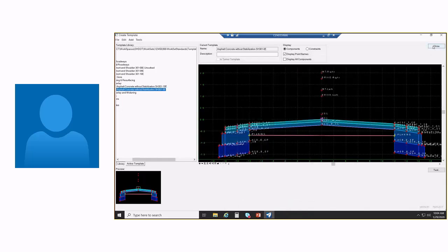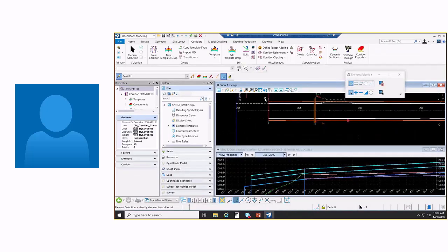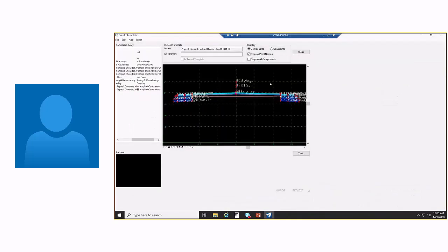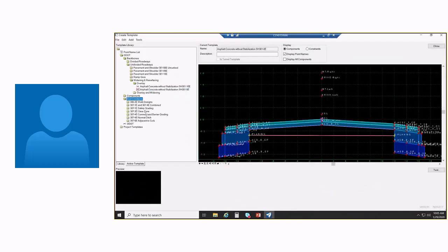So to some of you that have been using this, that probably makes sense. But you'll know it's a problem if you assign a point control and it doesn't apply. If there's a feature name override assigned, then that's a bug currently. Anything else I need to mention? You typically see it when you're doing your ditch profiles, because the ditch point, that's where the majority of people see it. Yeah. And they go, why isn't that ditch point showing up? That's why. Just go into that and just uncheck the feature name override, and then it'll show up.